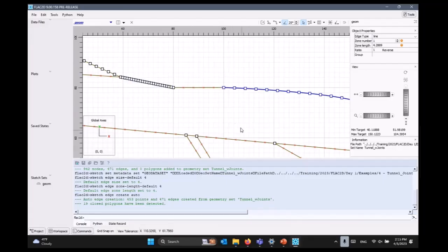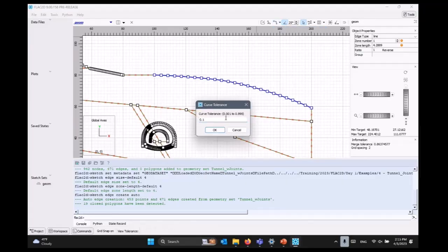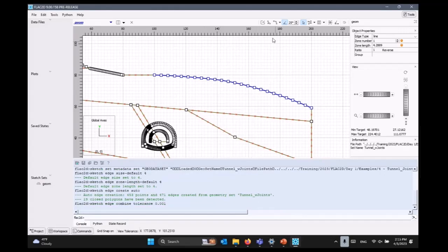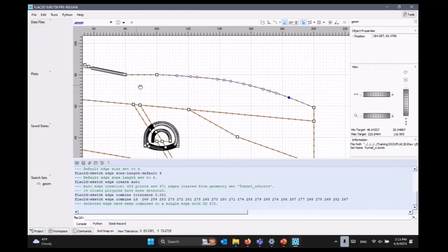And now it's deselected. And now I'm gonna press combine these edges, but I'm gonna specify higher tolerance, so the new edges will stick closer to the original shape. Then I'm gonna press here. And now it's my new edge with control points. It became a curve that fits to the original shape. That curve is actually called this line with multiple control points that regulate curvature.